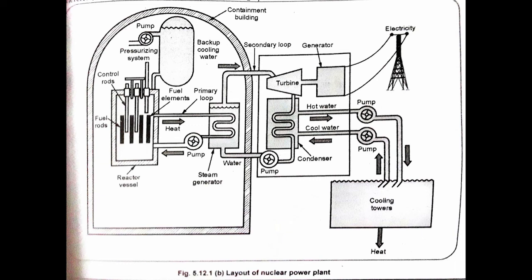This shaft is also connected to an alternator which converts the mechanical work into electrical power. The electrical power is then connected to the grid via a transformer. The steam which is expanded in the steam turbine is passed through a condenser where it is condensed into water again and can be reused. The condenser has cooling water which is circulated as the tertiary loop, or the third loop, of the nuclear power plant.